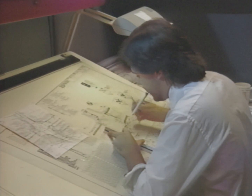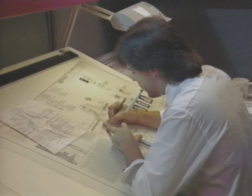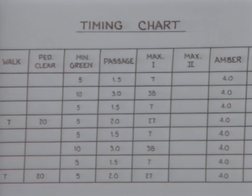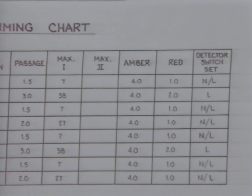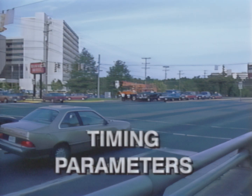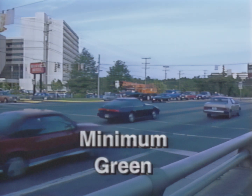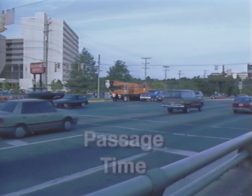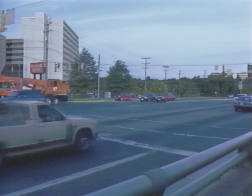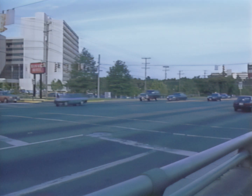Once the detector type has been chosen, the next step in the design process is to select the type of timing intervals for the intersection controller. These timing parameters directly relate to the detector type and low speed versus high speed approaches. Normally, in an actuated phase, there are 3 timing parameters in addition to the yellow and red intervals. First, there is the minimum green, or initial interval. Next is the passage time, also known as the vehicle interval, the extension interval, or the unit extension. And the maximum green interval is the last timing parameter.